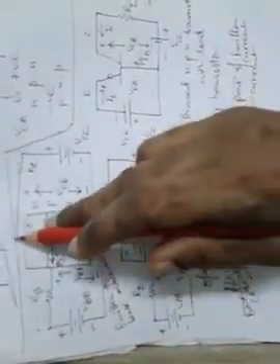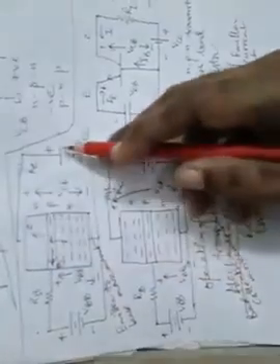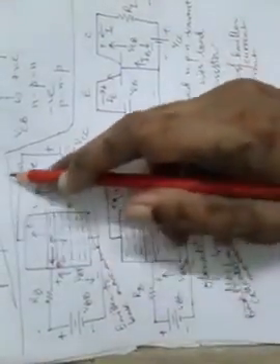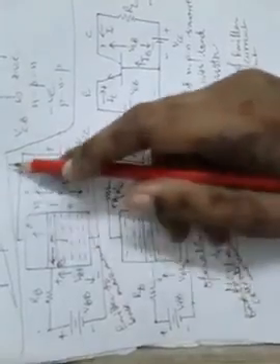So this is the way the transistor will work. Now the major number of free electrons will be collected by the collector, and they will naturally face the attraction of the positive electrode of the source VCC, and they will move through the collector resistance to go inside the VCC source.